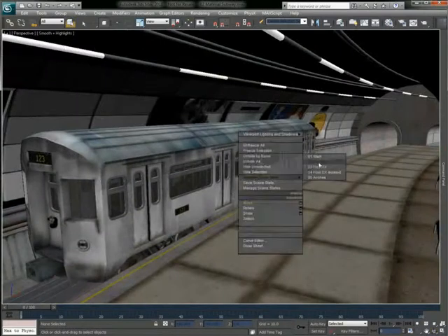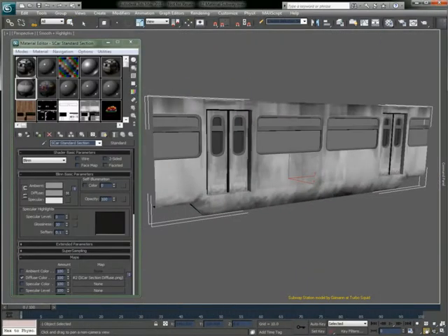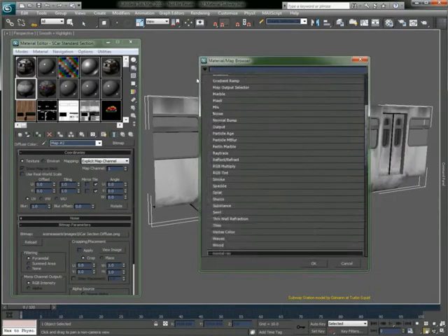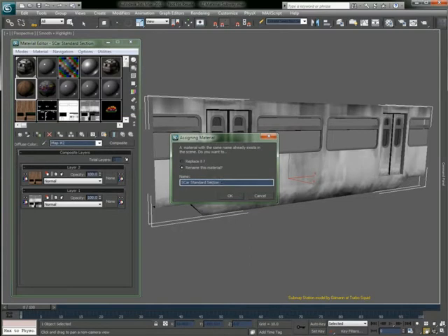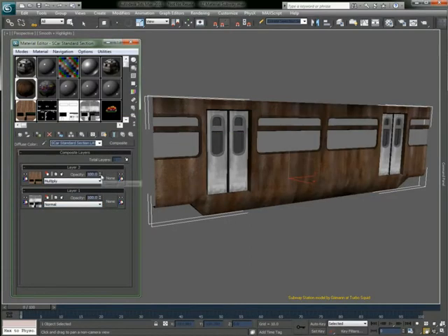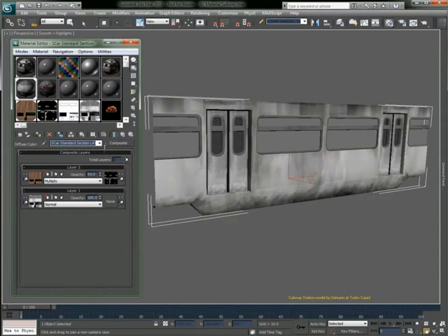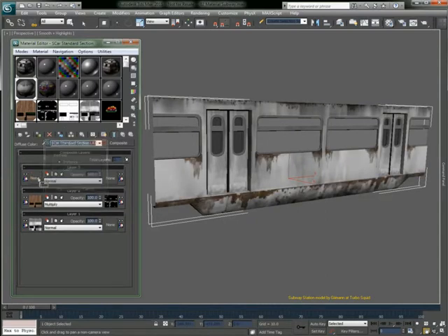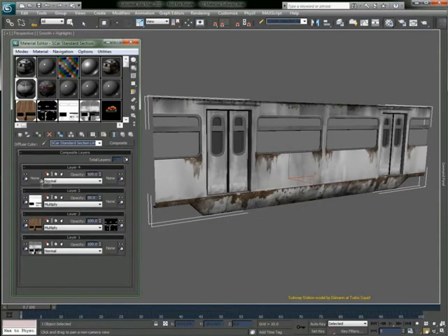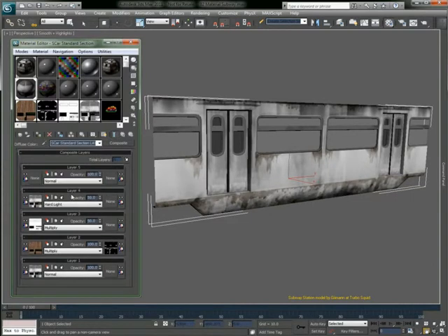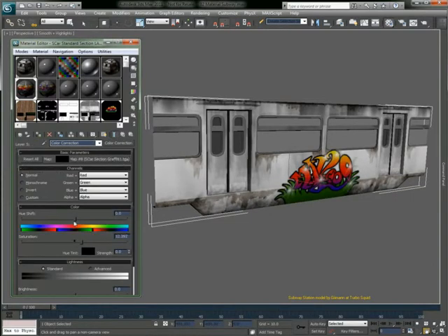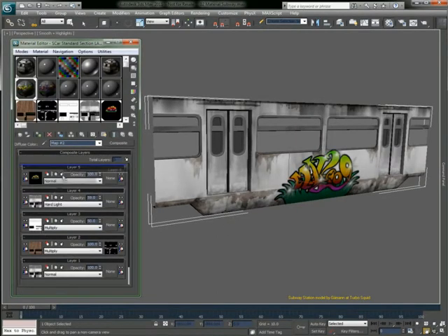If that wasn't enough, yet another way of working inside 3ds Max with layer-based materials is by using a simple yet powerful map type called the Composite map. What the Composite map allows is for users to quickly and easily stack up any other 3ds Max map type and combine them using any combination of layer opacity, blending modes, alpha channels, and built-in color correctors per layer. These composite layers can include procedural textures, substance maps, bitmap textures off the hard drive, and textures generated by either Viewport Canvas or the Render Surface Maps utility seen earlier.